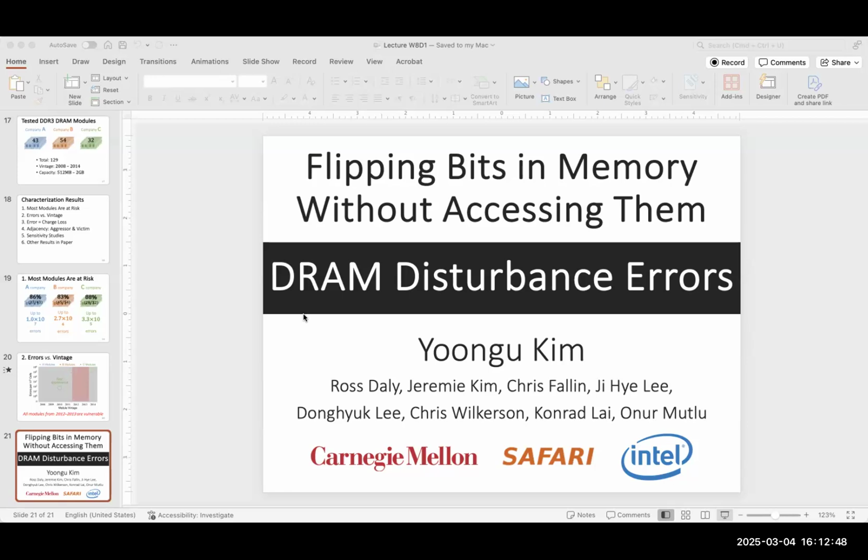So we want to efficiently store a large amount of data in the memory, and this is how our memory looks like. It is just an array of memory cells. We give an address, which is n bit, and it gives us data, which is m bit. The data arrow is bidirectional, which basically means we can write the data to this address, or we can read the data from this address.